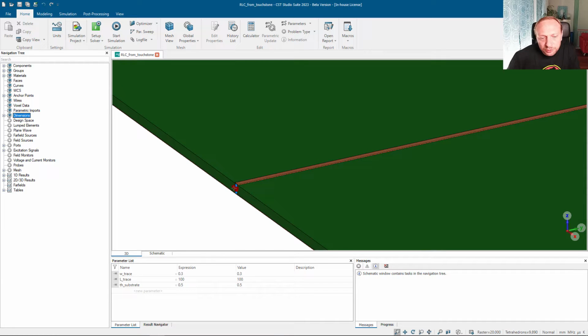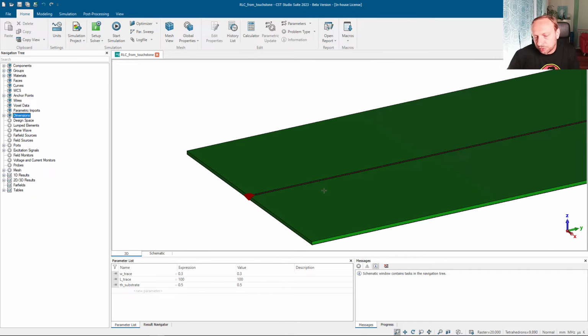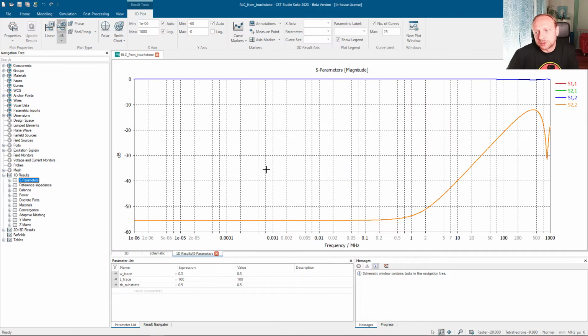It might be the same as when you do a measurement, putting an SMA connector, inner of the SMA here, outer of the SMA here. And when you do the measurement, or when I do the simulation, what we get is of course the S parameters that tell me, okay, I have a great transmission, it's a well-defined system, there are not many obstacles, and you don't expect any impedance changes. But that's basically all that we see from the S parameters.